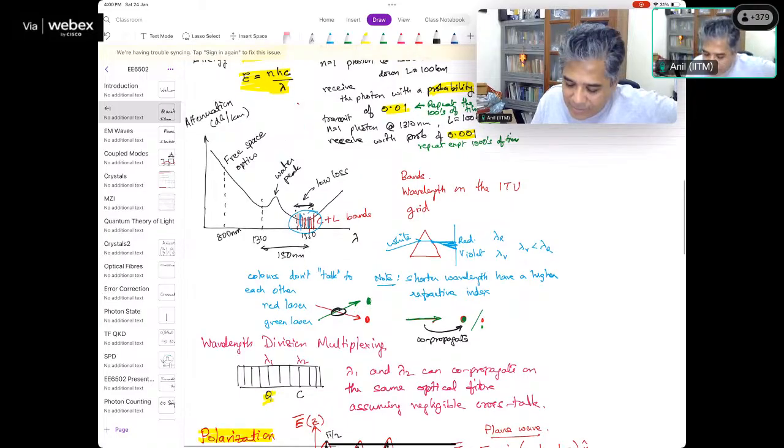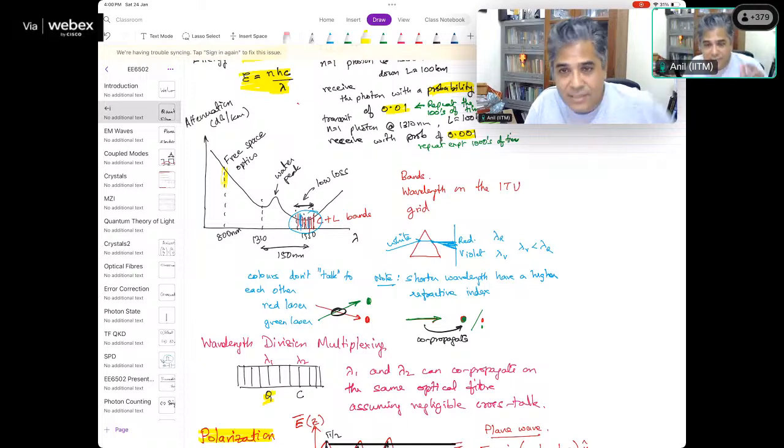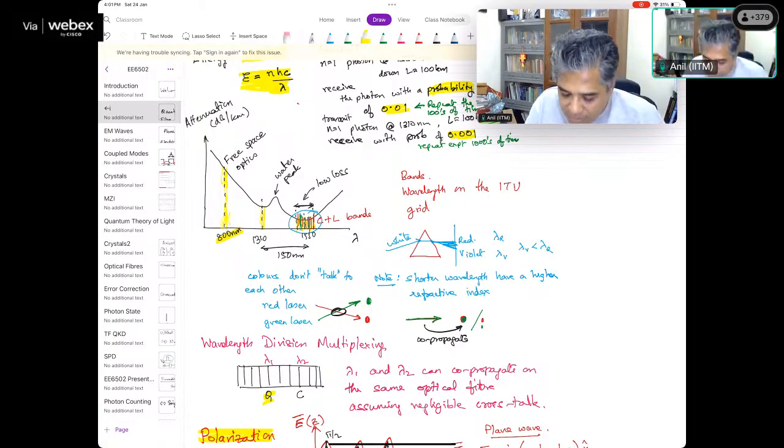I was referring to this chart out here. We call them the windows of optical communication because there are three wavelengths. There was this 800 nanometer range. There is this range of wavelengths around 1300 nanometers, so we call them windows. And here there is this range of wavelengths around 1550 nanometers. These wavelengths are not unique, 800 nanometers, but there's actually a range around it. That range is what we're calling a window.